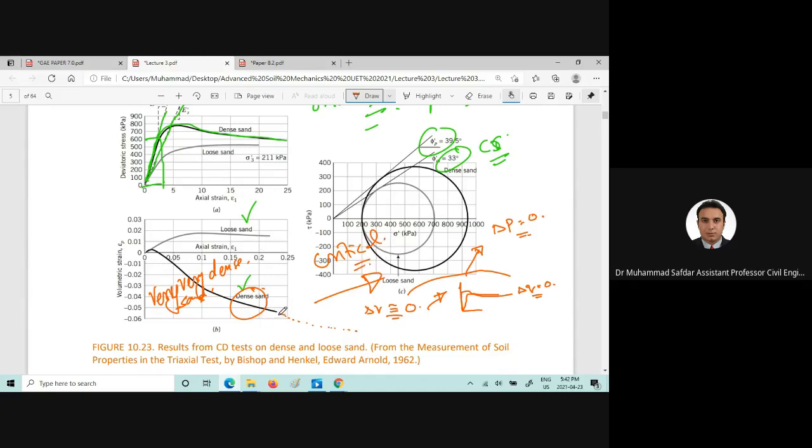So this is the limitation of the triaxial test, that you won't be able to reach it. I tried this in my PhD thesis as well, where we were able to reach about 30% axial strain. Now Wali is talking about the clean sand, where we are unable to reach that critical state. I tried even 35% axial strain, and that was the maximum axial strain I could reach in the GDS apparatus.